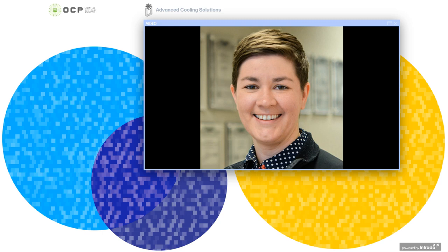So I got a follow-up question to the cycle test. If there is a failure after 10,000 cycles, what does that failure look like, and what components fail the most? That's a good question. I'd say typically the failure mode isn't going to be anything structural or mechanical, really. Typically it's going to be associated with wear of the elastomers.